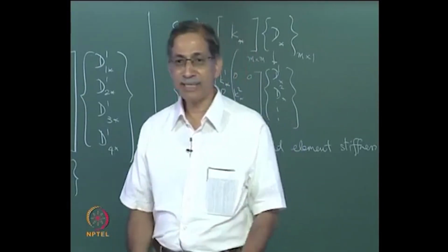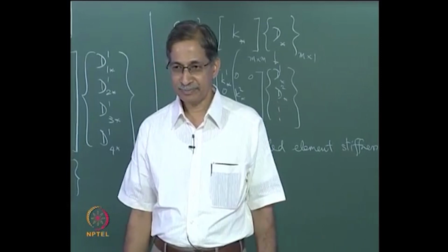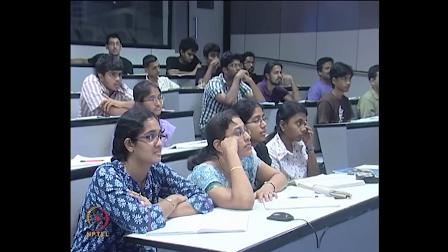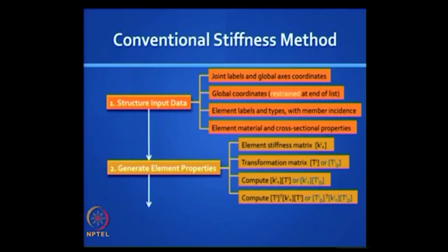Next step, what do you think is the next step after you have given the input? That comes much later. I mean, I am not saying what you have to give, you are right, you have to give the loads. What is going on inside? The moment you give this, it is not waiting for loads, it is trying to be ready to handle your loads. No? So by the time you key in the loads, it would have done its homework. What is the homework? It will generate the element properties, right.